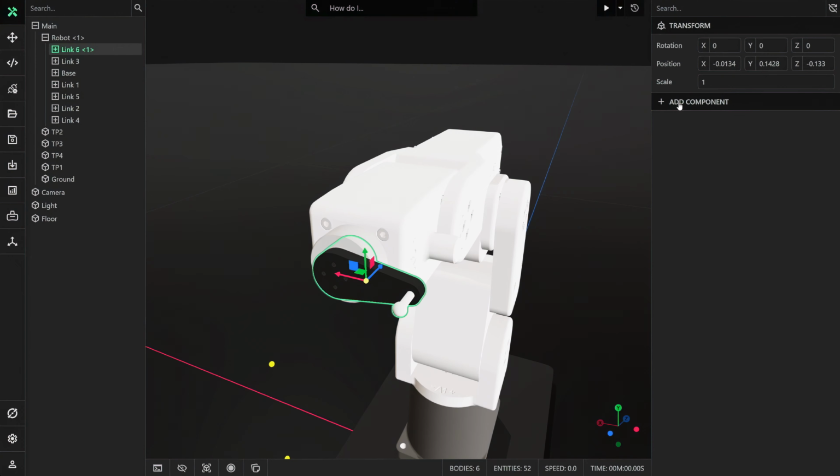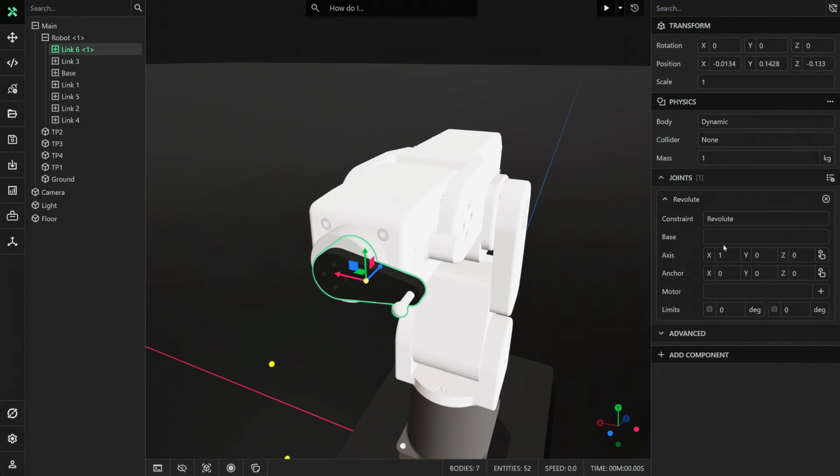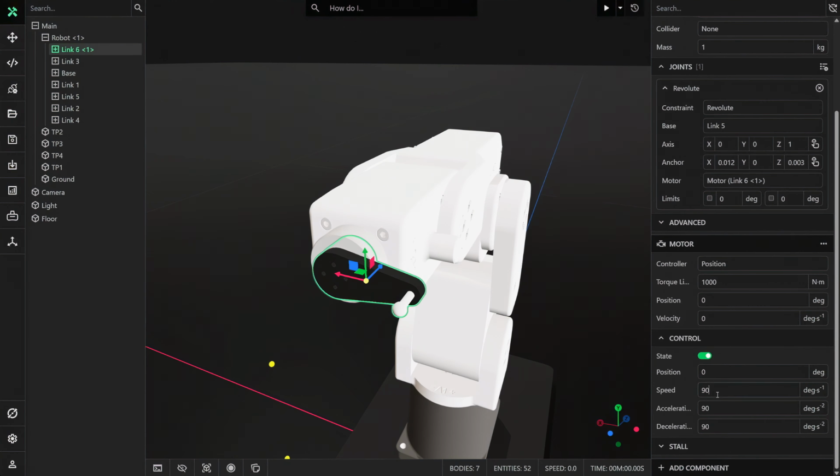It's not a strict requirement to apply joint limits for this model, since all the moves used here are valid moves. However, it is still worth applying them in other robot models you make, since the robot controller component in ProtoTwin will automatically detect any moves that violate the joint limits, and will output an error whenever the robot is unable to solve the target.